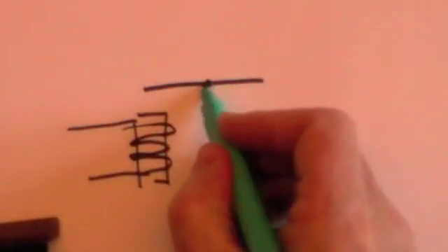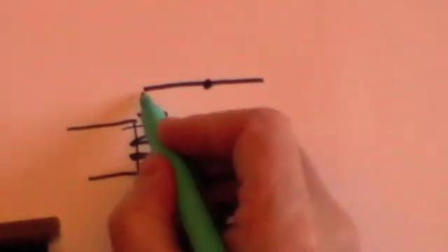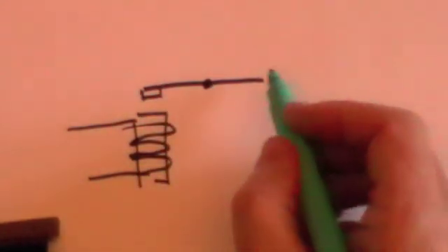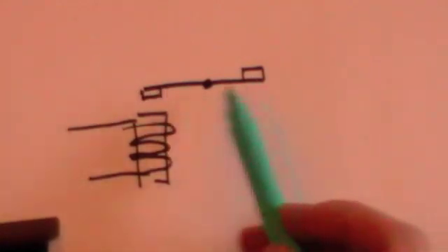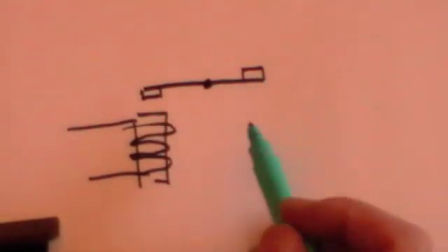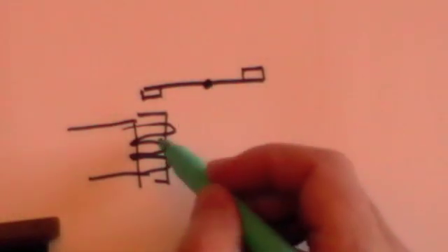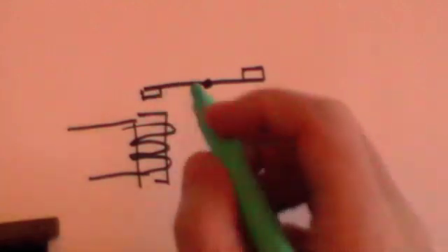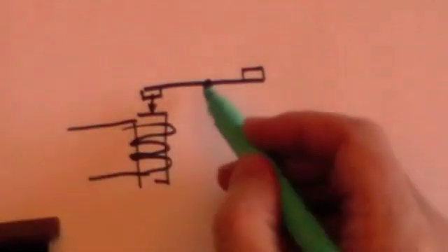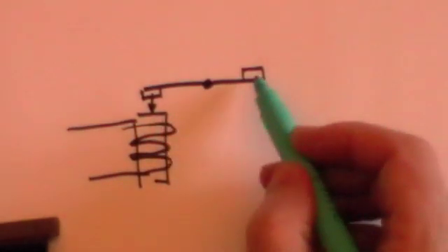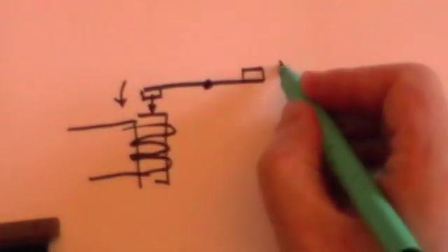Now what you then do, I've not left myself much room, so I'm going to redraw the magnet down here. Here's the magnet with the coil around it linked to the logic circuit. What you do is you have a pivoting arm made of insulating material. But at the end of here you have a piece of metal, and at the end of here you have a piece of metal. But this is insulated, remember, so no current will flow in this piece of material here, only metal at the end. What will happen if this becomes a magnet? That magnet will attract that metal, and the metal will swing down on this pivot to touch the magnet, which means that this end will swivel up. If this end swivels down, this end swivels up.